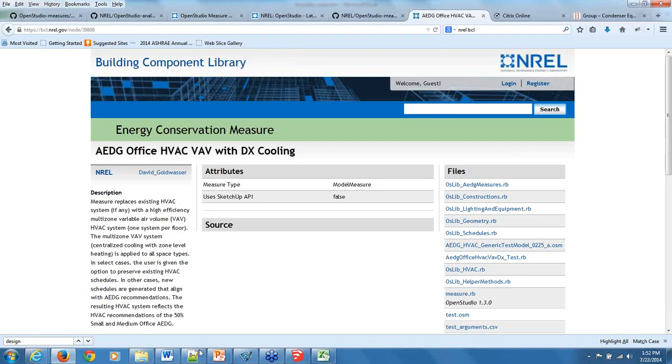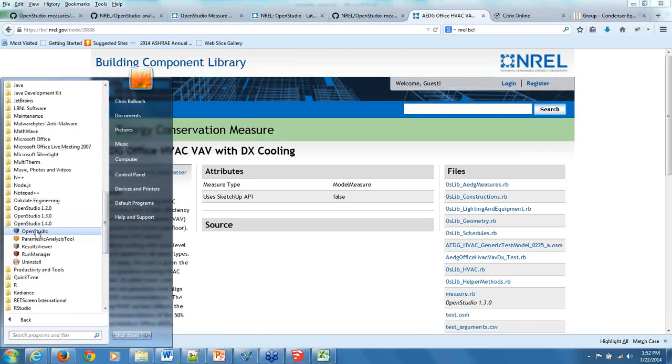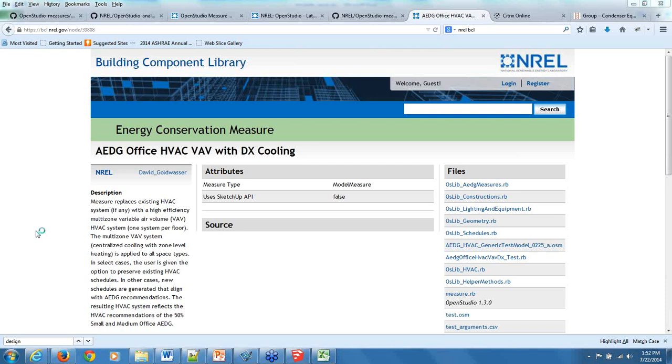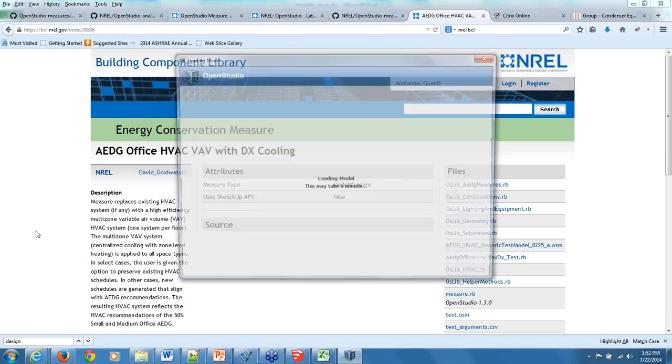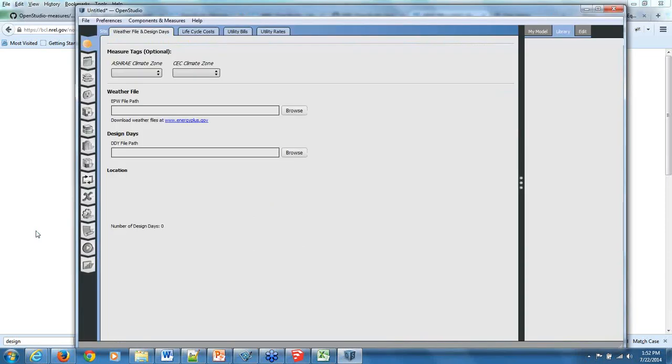So just to show you that again, I can just open up the OpenStudio application, and we can apply that measure at any time. We do not have to simulate the model, we can just use it again to change the model that we have. That's a very, very powerful feature, combining this new Apply Measure Now with very innovative measures in order, again, to get the type of model that we want.